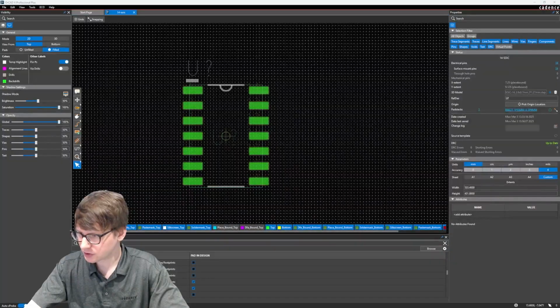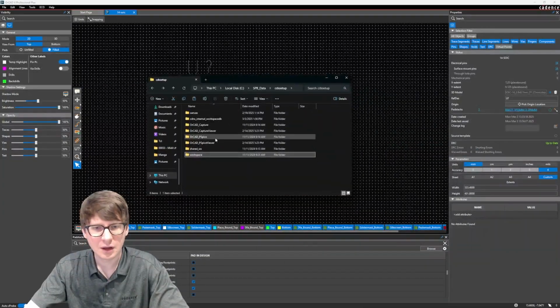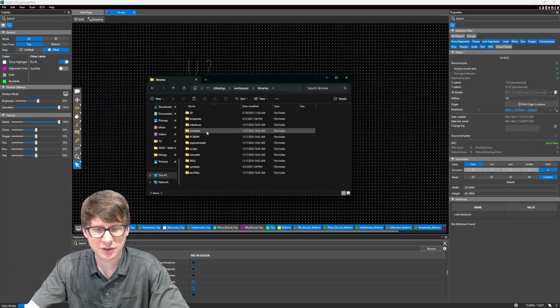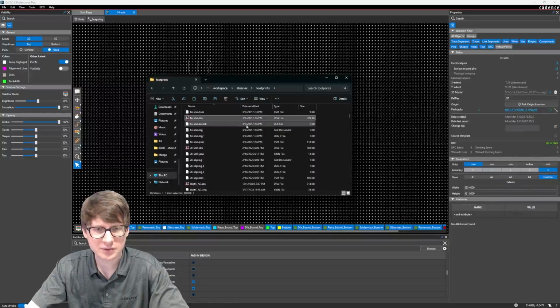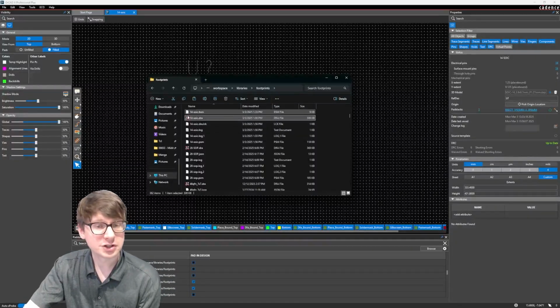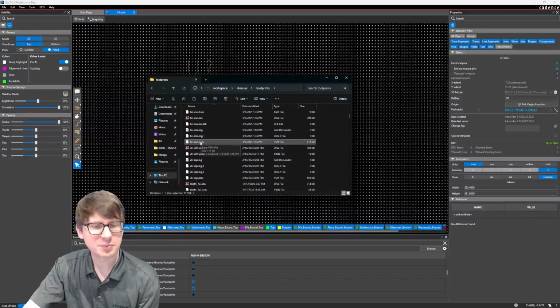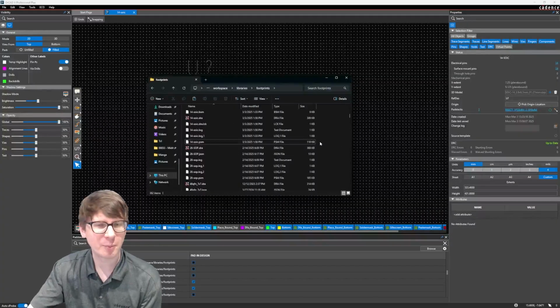And one thing I just want to show you guys really quickly is that when you save, let me get to my library here. When you save that, and we'll go into our libraries, footprints, and we're looking for the 14 SOIC. One thing that you should check is make sure that you create the DRA save file, and also you want this PSM file, which is basically just like a packaged or compiled version of the footprint, which is what actually gets used when you place that on your board.